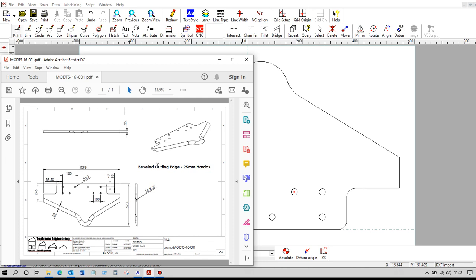Now to create a contour that we can use with a Z profile or a constant taper angle, we need the top edge of the curve rather than the bottom edge. So we know that it's 50 millimeters and it's 25 thick, so it's an angle of 45 degrees. So we just need to create some lines parallel to the bottom contour.